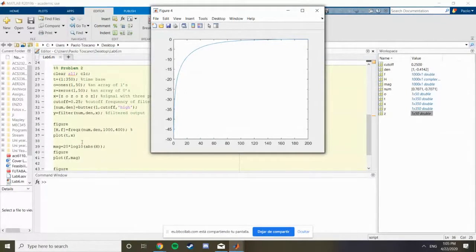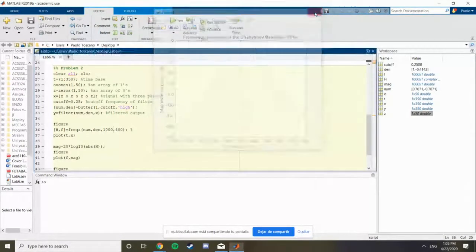Of course, this is a Butterworth filter. It doesn't have a lot of ripples, but generally, a rule you can consider is to look at the frequency range you have from 0 to half of the sampling rate and estimate what would be a good resolution for you to plot the filter. I would say consider 4 or 5 points per hertz.